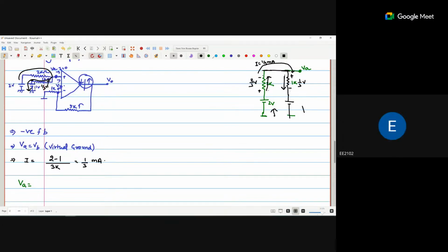So what is the voltage at this particular branch? Positive and positive. Okay, both are the opposite polarities. Same polarity are connected. So that means the voltage at this one is 2 minus 2/3 volts. That is 4/3 volts. Or you can calculate the voltage from here also. So this is the negative and positive connected.